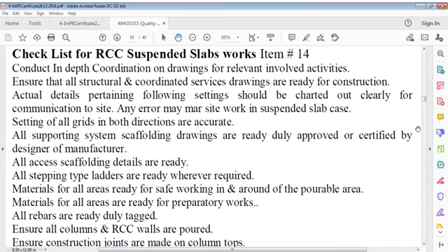So there are two ways. Either we take from the pouring slab down, to the upper portion of the wall, all electrical services requirements, or you might have taken from below for near-floor requirements. Those inserts, those electrical conduits and others have to be placed on the current slab. So this is a kind of coordination mechanism you have to apply.